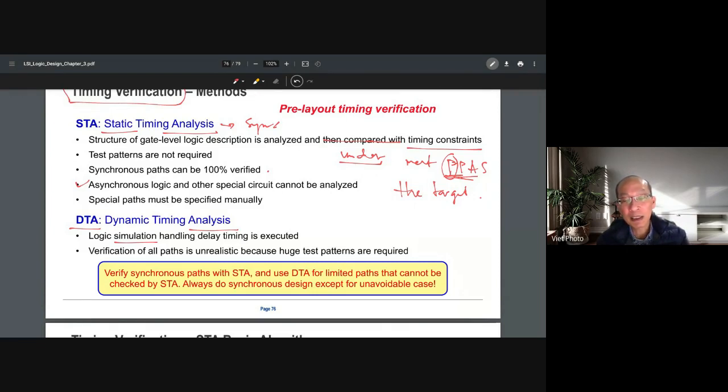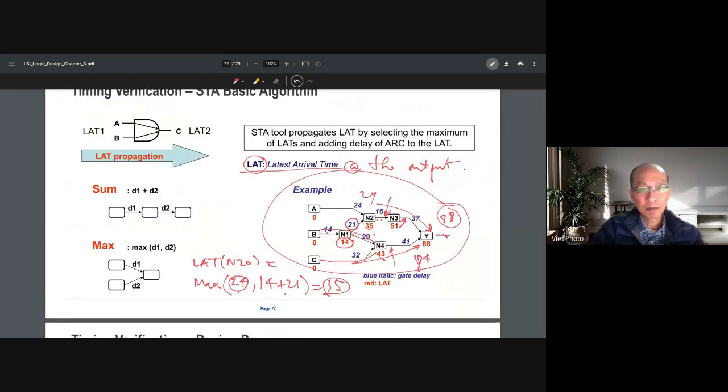That's because of PrimeTime, the STA, it checks every node and runs the calculation, so it runs a very long time. For the purpose of the lab, you run that quickly, but in real life it's very long.